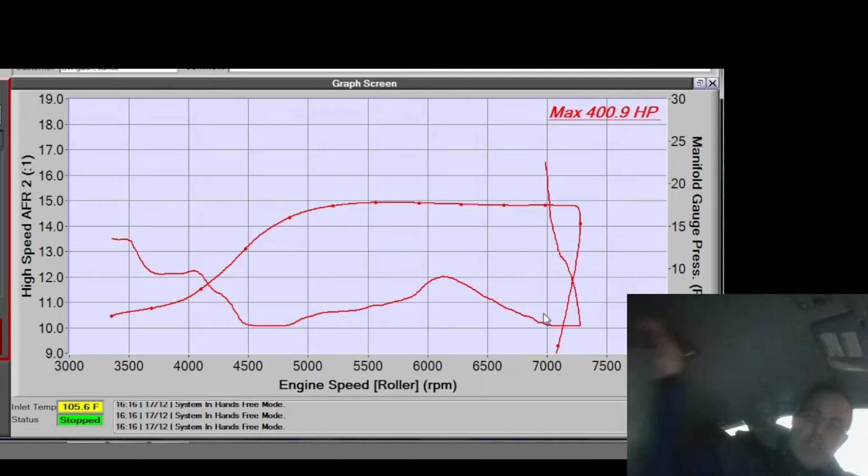I wonder if he blew a hose off. My idle seems kind of high now all of a sudden. What's my idle at? Idle target's 850, currently at 1050. Yeah, okay. So we'll pull the hose off or something. Take a peek at that real quick.